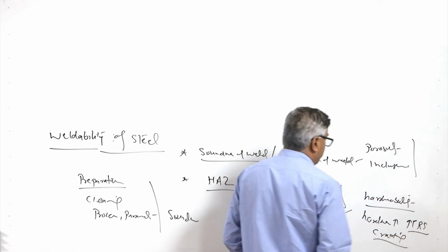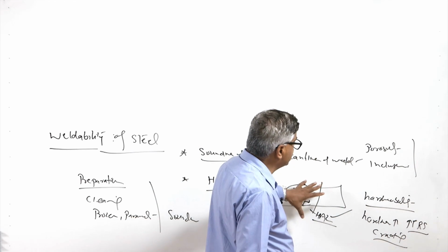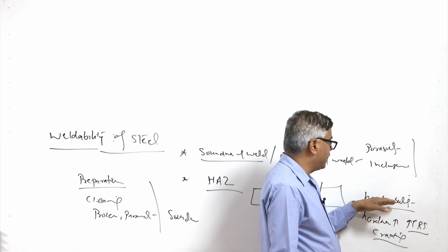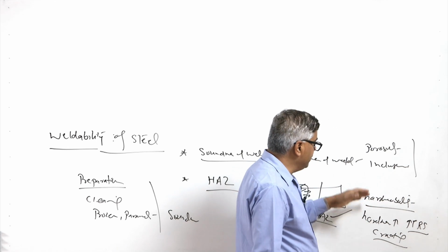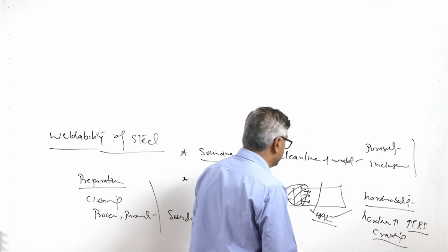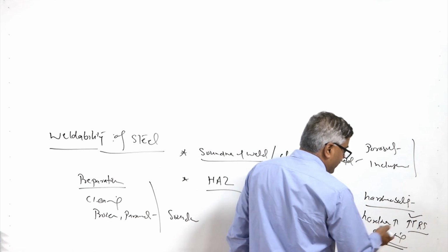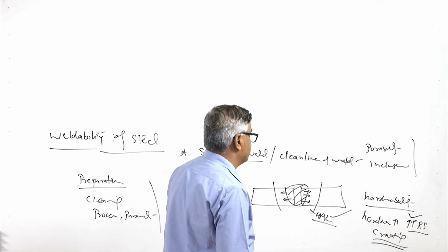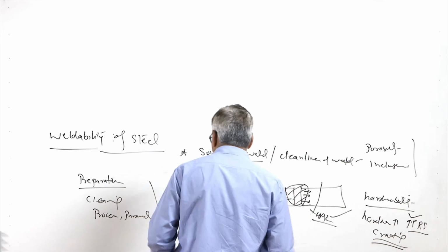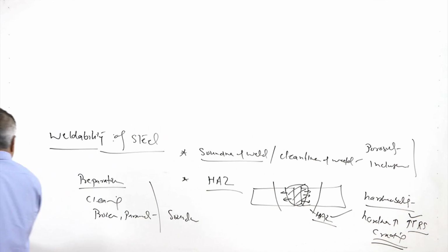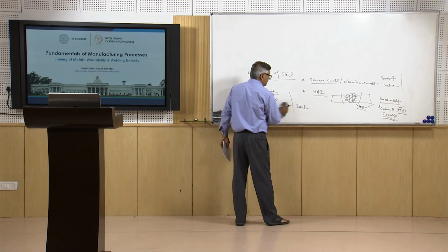That is why whatever factors related to the steel lead to an increase in weld hardenability, they will increase the hardness of the heat affected zone, and due to the tensile residual stresses, an increased cracking tendency is observed. So, we need to consider the factors which increase the hardenability of the steel.